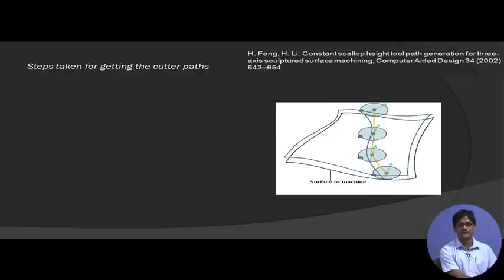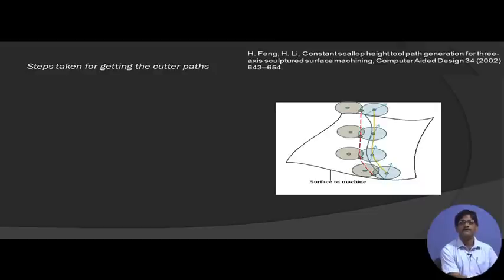of the cutter. So, these mark the tips of the scallop, the whole scallop geometry all through these particular positions by the side of the first cutter path. Next, we remove the scallop offset surface. We pass a smooth curve through these scallop tip points.